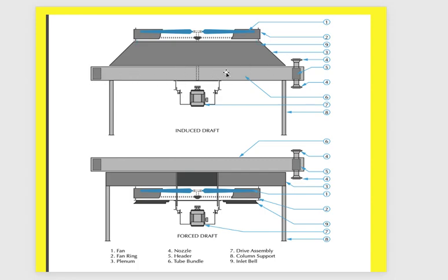And this is named a fin tube. Why fin tube? Because these fins increase the contact area between the surface of the metal and the air, which increases the cooling capability. Fin tube, okay? Here is the place of the fin tube. It transfers heat from the hot process fluid to the surrounding air. This is the function of the tube bundle.